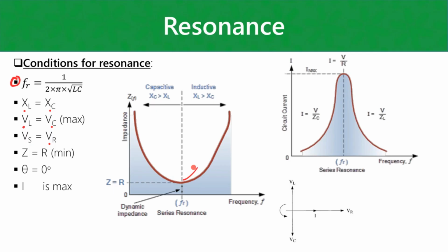And at frequencies above the resonant frequency, your circuit is going to act like an inductive circuit, more like an RL circuit. You guys will see that at very high frequencies, as the frequency tends toward infinity, you're essentially making your circuit an inductor in that sense.